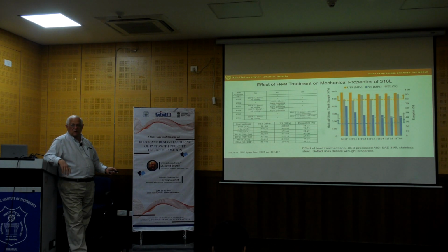NHT is not heat treated, so this is straight out of the machine. The ultimate tensile stress is in orangish brown, the yield strength shows up blue, and the percent elongation is the gray curves. So the elongation line is over here, and the strength is over here.